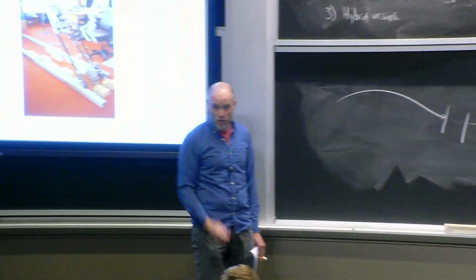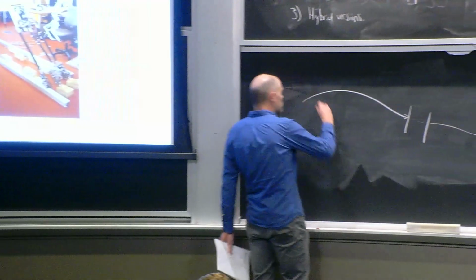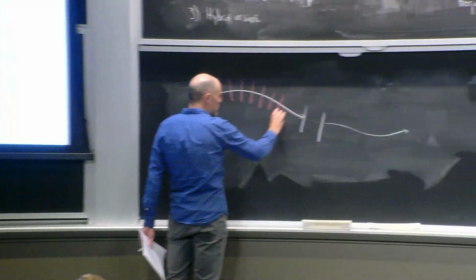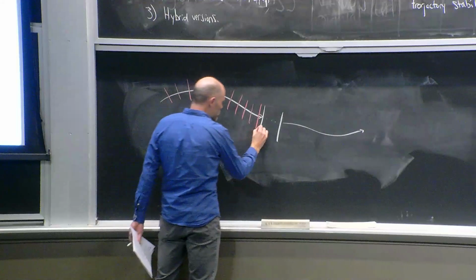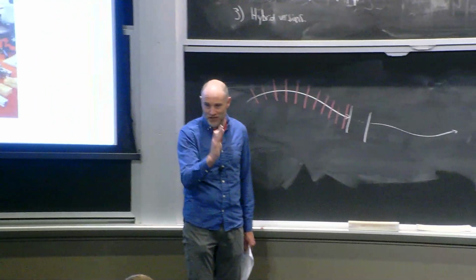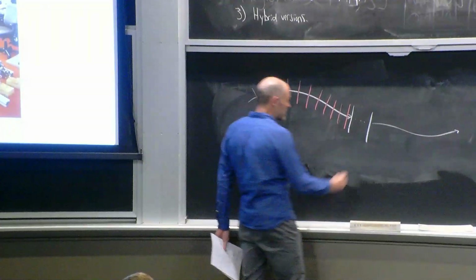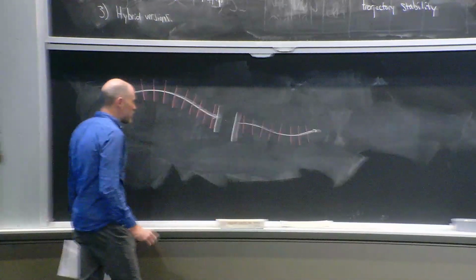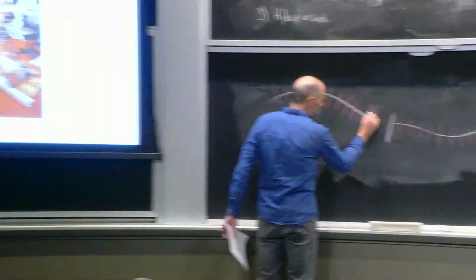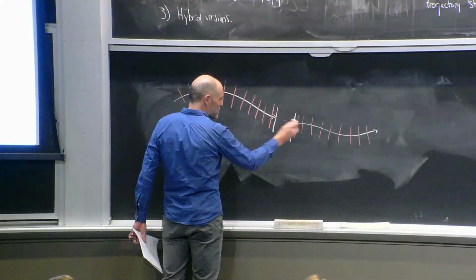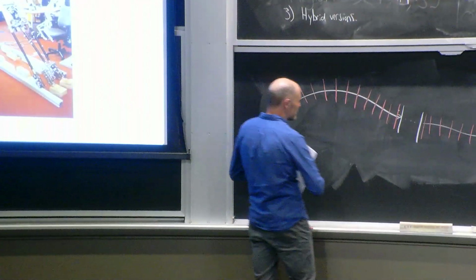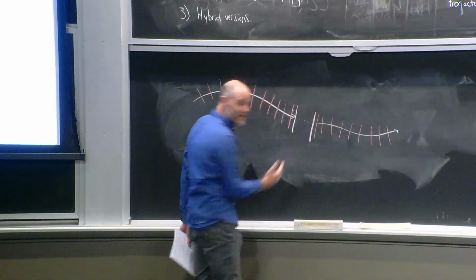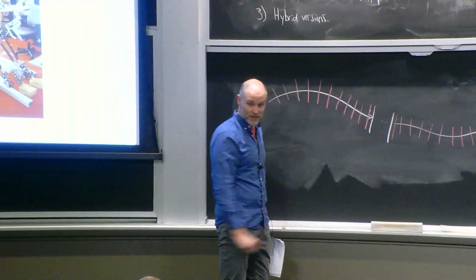Well, if you do the transverse coordinates, there's freedom, there's an algorithm, let's say, for picking your transverse coordinates. But one of the things that you want to do is line up your surface of section with the linearization of your guard. It's not strictly necessary, you can accommodate all these other things, but it makes everything much easier to analyze. At least locally, transitions from this surface of section move to this surface of section, and you can analyze the dynamics in pieces. You can look at V dot being less than 0 along here, and delta V over the impact being less than 0 in order to converge.